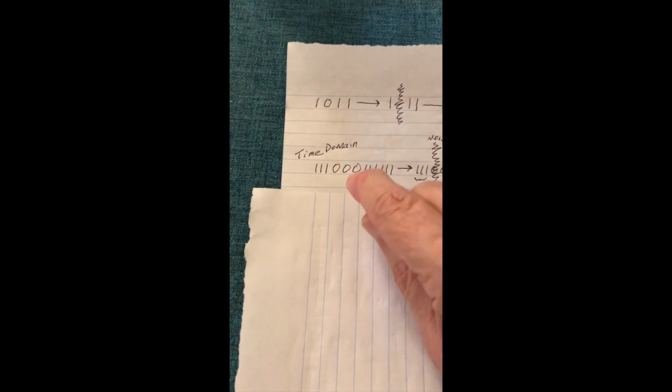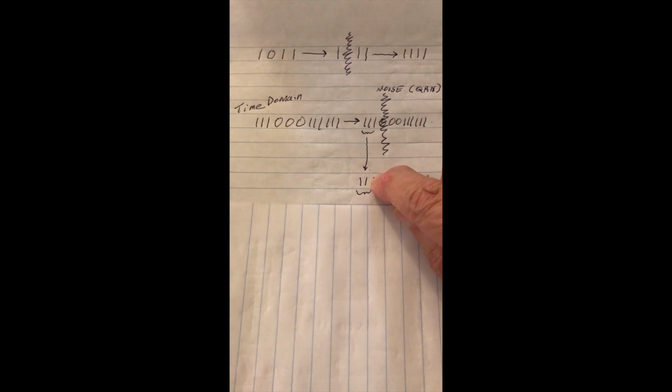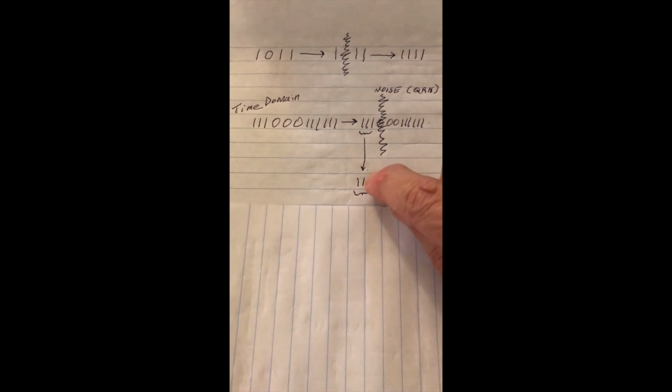And so we repeat the 1 here 3 times, the 0 3 times, the second one 3 times, and the last one 3 times. And then if we get a source of noise, which in ham radio jargon is called QRN, N for noise, I guess, if there's some noise that wipes out one of the zeros here and probably replaces it with a 1, we can detect that fact in the receiver and realize that if a majority of the bits are ones, then we should decode this as a 1.